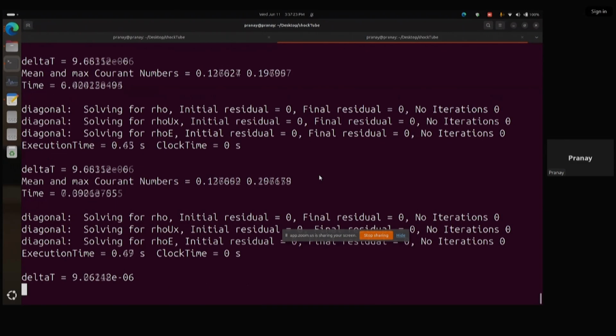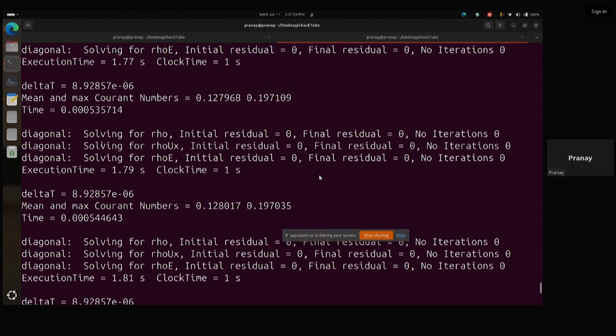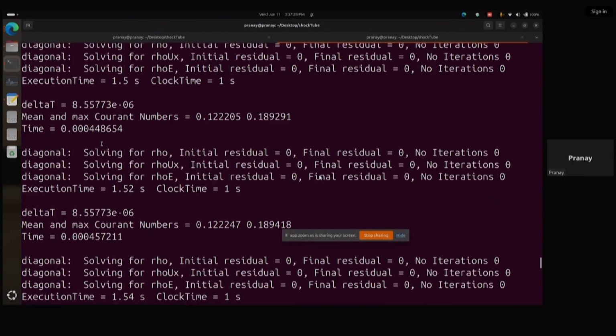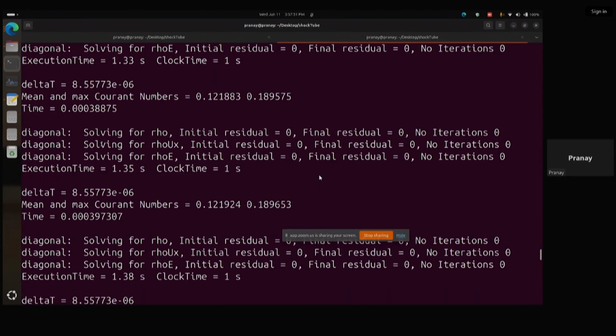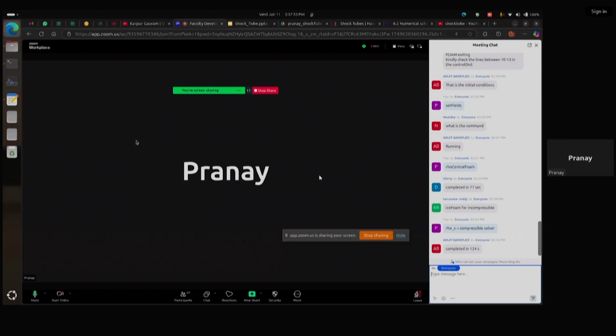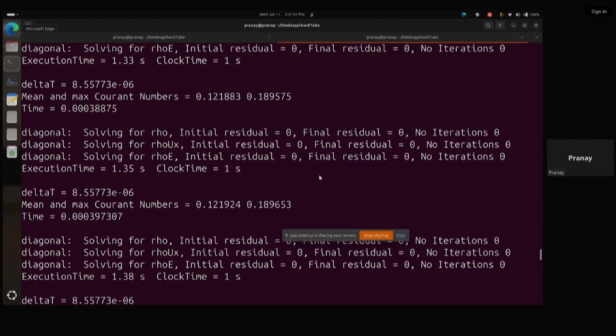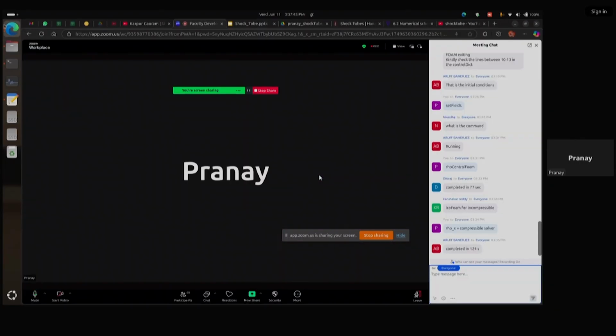Let me show. Even in the beginning time step, it's zero. The physics governing this case is set up in such a way that we are not focused on the residual part. But if you want to see the residual, you can try the simpleFoam case, the pitzDaily case of yesterday. Pause on the screen, and you might see the residuals decreasing as time increases, and after one point, the solution becomes converged.